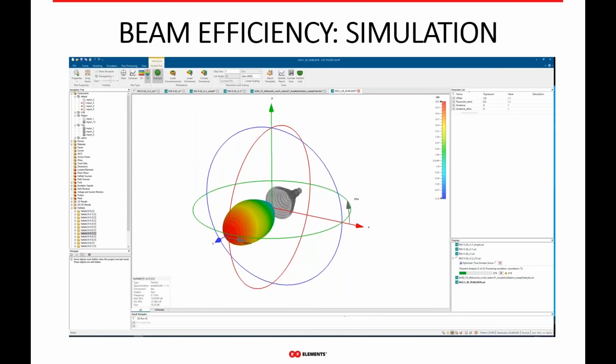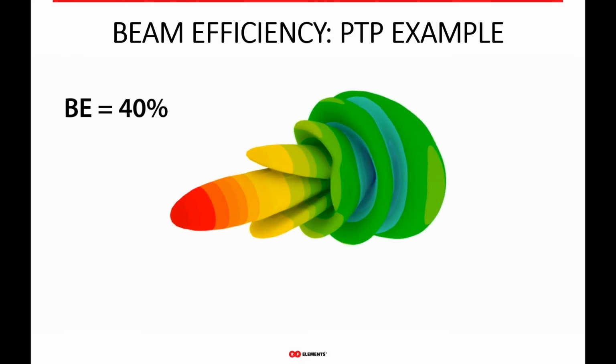If the model of an antenna is precise enough, or an antenna pattern is simple, we can also use simulation software to do the same thing. So, basically, obtain the radiation pattern, and based on that, we can calculate beam efficiency. Some simple beam shapes allow you to simulate beam efficiency and get it without having to measure it, so it makes it a little bit easier.